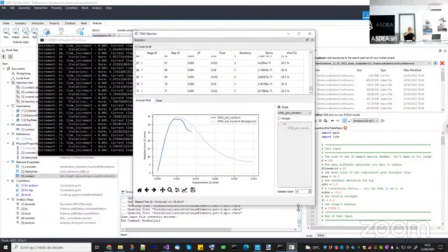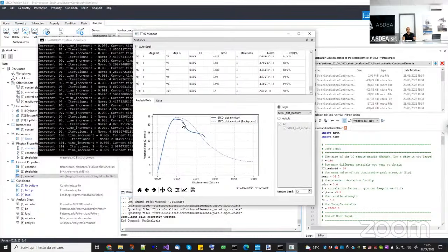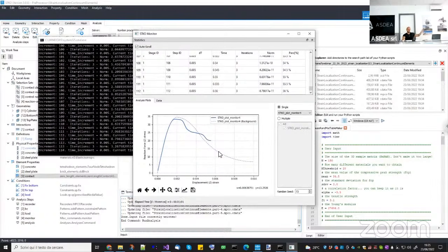Now, of course, it will never be perfectly equal to this one, because to have a perfect solution as this one, you have to use a perfectly constant state of stress. This is not possible because it is a three-dimensional problem with contacts, very complicated. But the concept is computing the real fracture energy, specific to the specimen, scaling it so that you obtain the real fracture energy from that specimen, then you apply automatic regularization. You add some imperfections and you play on the boundary condition.